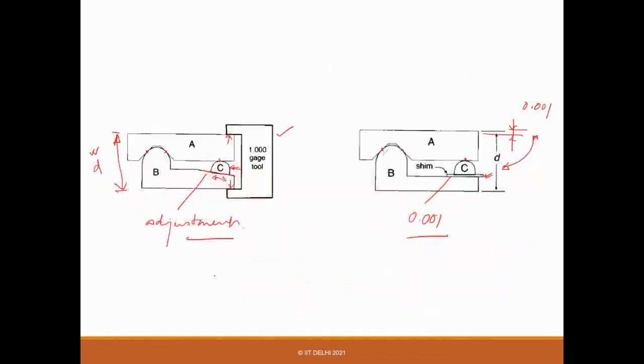And that's what you are doing here. So with the exact constraint design, you achieve the repeatability, and if you provide a way to adjust later, you'll be able to achieve accuracy as well. I think that's the fundamental, and that's the very basic principle in designing any precision equipment or machines.